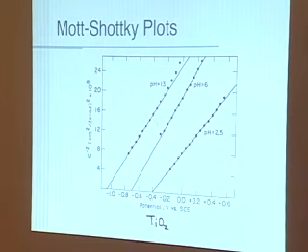That energy is close to the energy of the conduction band, and if you tell me how much dopant is around, I can tell you exactly what that spacing is, but usually close is good enough. And so I know this point, when I measure that. And I know the band gap from the prior photoaction spectrum, and therefore I know this point.